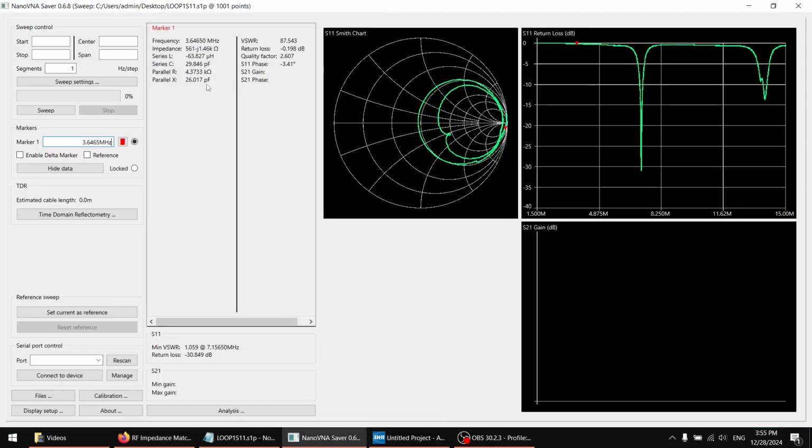You can see that we are given this value, of course, in positive picofarads because of where the point on the Smith chart will land. And as you can see, it's very close actually to this crossing point. And because this resistance value is very high, we are almost at the open side of this Smith chart.